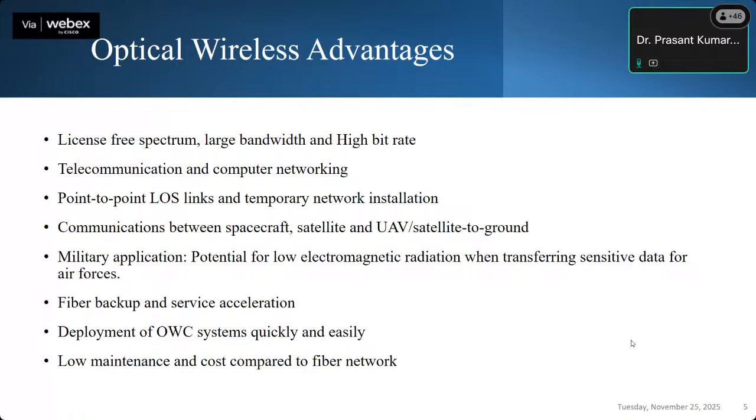The bit error rate, I'll show some results where you can see that the BER is coming around 10^-9 for a distance up to say 9.5 to 10 kilometers, which is a significant range for an optical wireless scenario, without using much of complex systems. So we designed very simple systems, where the target was not to use many amplifiers and also not to make the system complex. So that's why we didn't use an encryption scheme. Rather, we thought of using a chaos aided system so that we can ensure the security, as well as the range.